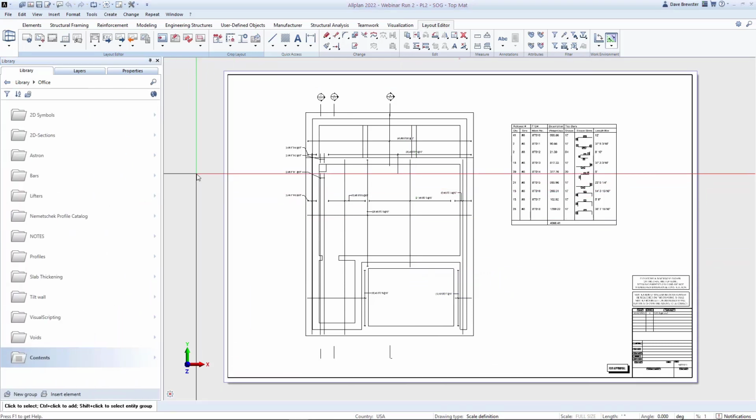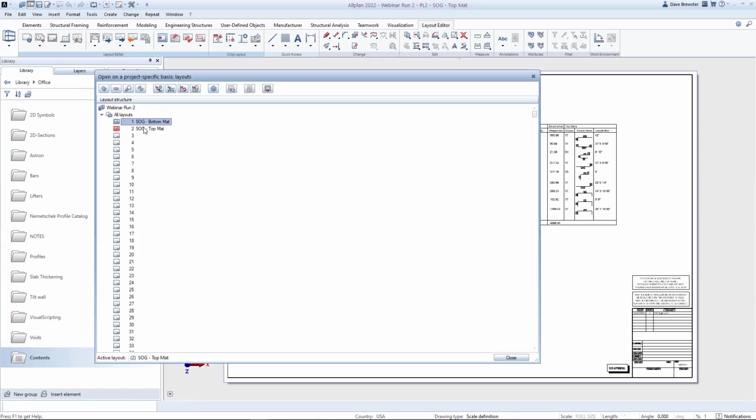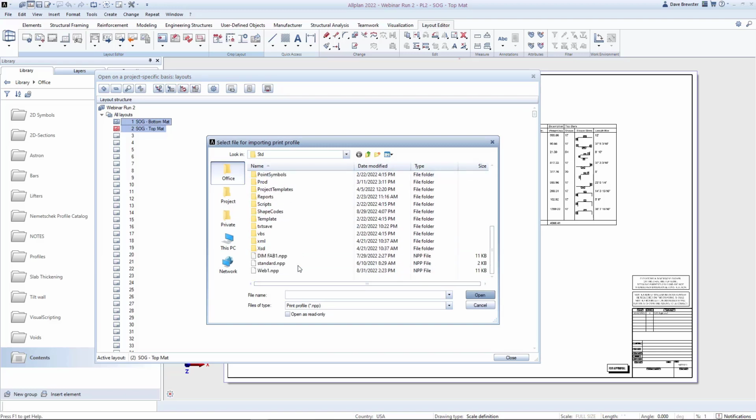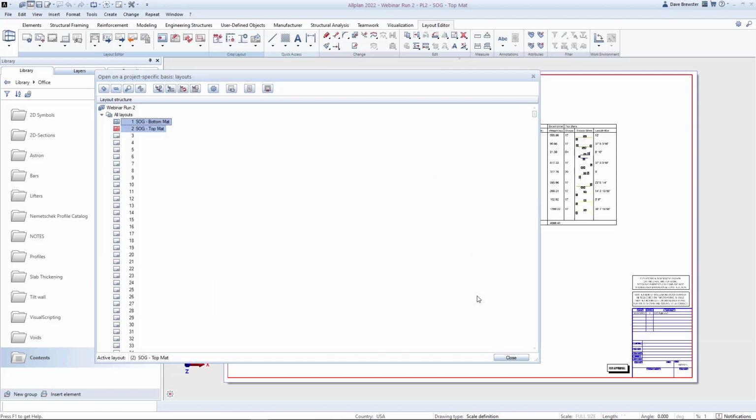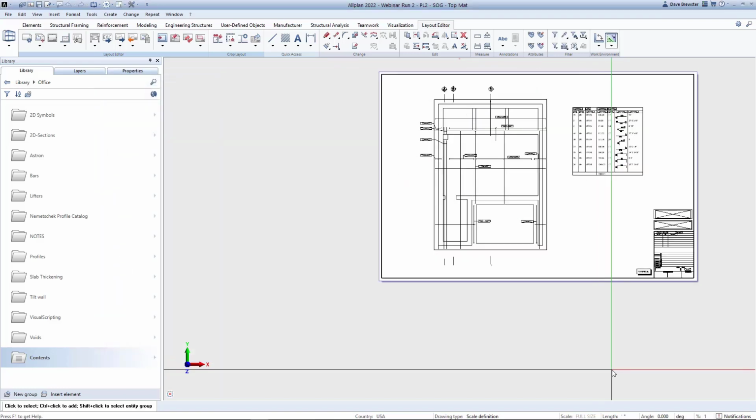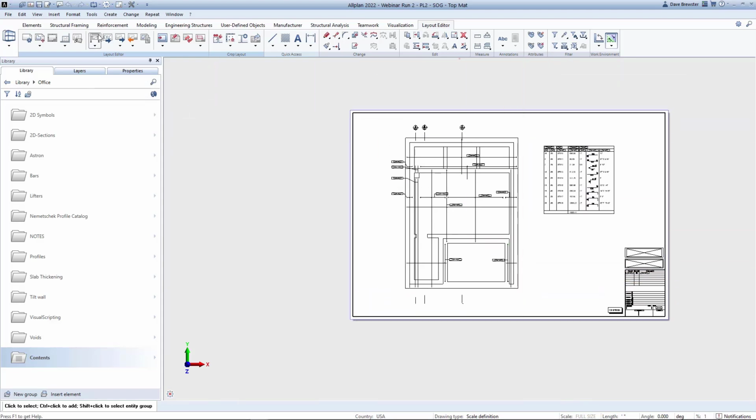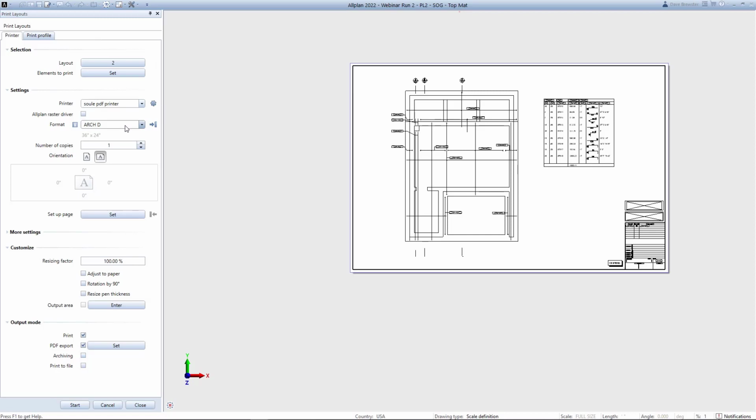Now a very quick way is each one of these drawing files, if we're getting ready to plot these, I can highlight this or 100 of them to say I have a print profile for these. I'll call it my web one, which I've already pre-saved, and it goes through each one of those drawings. It sets a print file. It knows which printer to send it to, the modification, the zoom, all that, which is going to show you here right now. It's a Silhouette printer, the size. Am I printing to a file? Is it monochrome? Is it just a paper?